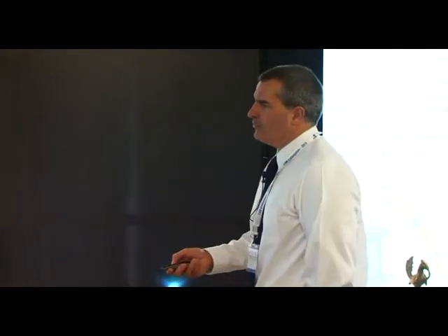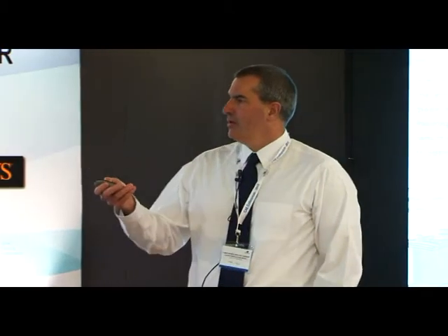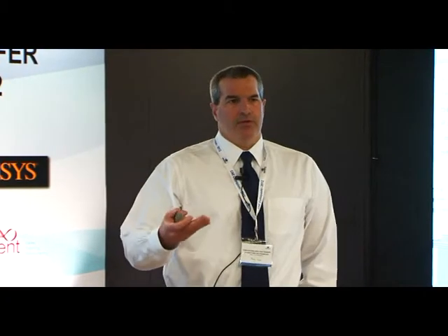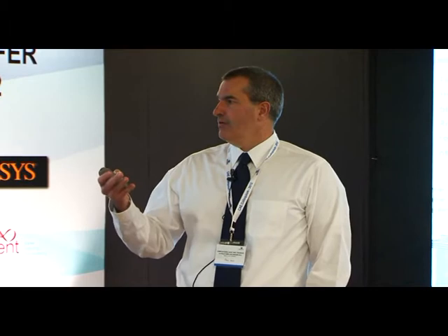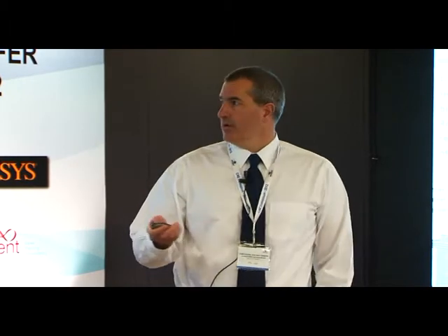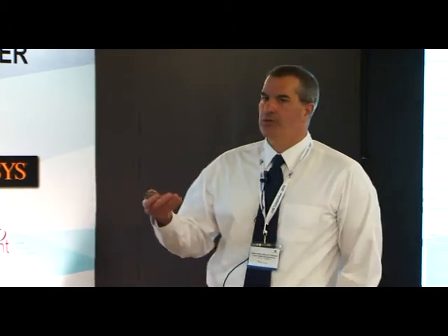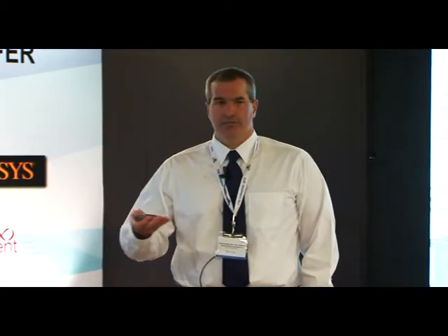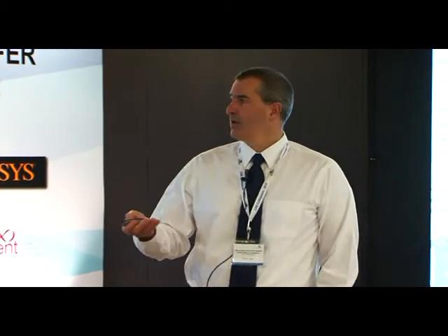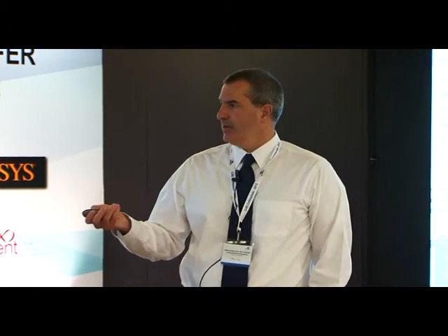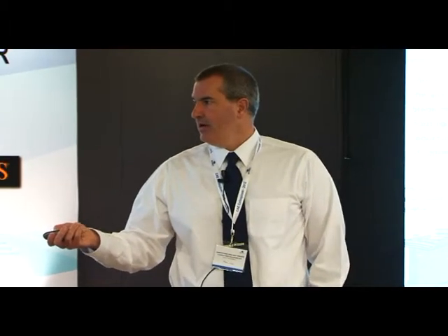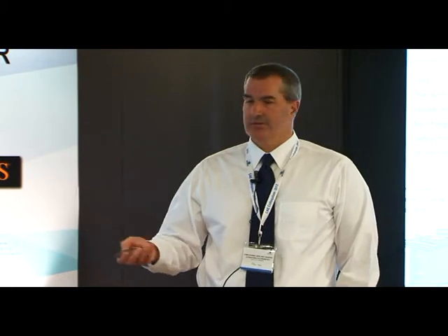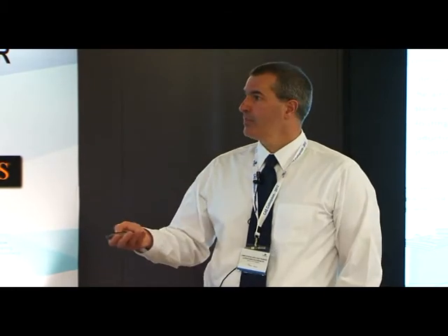Film cooling is, the way they go about it is you take your blade and you drill a large number of holes in it. The concept here is that you want to take cooler air, which you pull off the compressor, and coat the outside of the blade with a layer of cooler air. And that's going to protect it. Just an example of that is shown for a nozzle. The concept is the same for a blade.